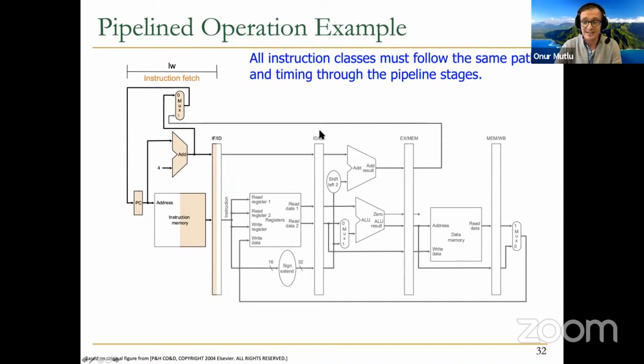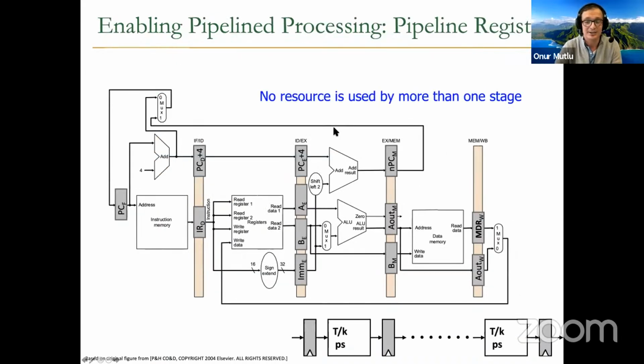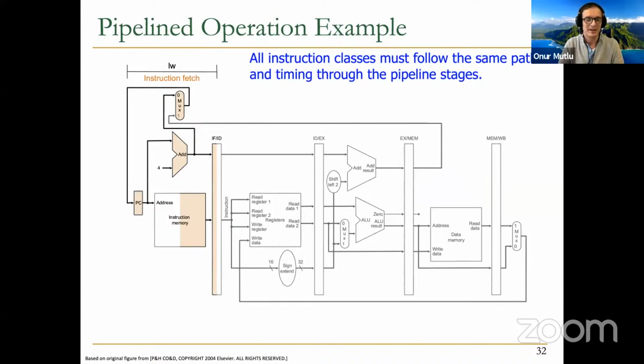Somebody asked, what about write data? I'm going to handle that later on. But write data, exactly, you have a very good point. You need to decide what to do with the write data, and we're going to defer that question until later. Basically, you need to decide when to write to data memory, and you should be careful about that also. In many pipelines, you delay the writing to the last stage. But in this pipeline, it happens to be in this stage. You need to be careful about how you report the results to the software as well, but we're going to ignore that for now. You have a very good point. We're going to deal with that when we talk about precise exceptions, either in the next lecture or in a later lecture. But very good catch.